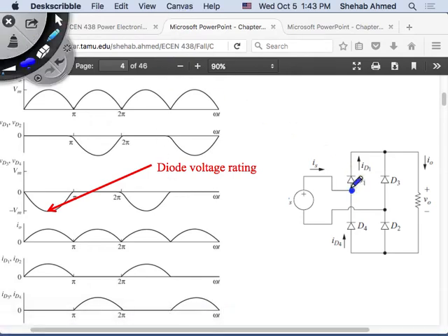So now we want to derive it. Typically, all you're concerned about is the source current. I'm the utility, I don't care what happens inside your converter. You do whatever you want. But you're consuming my current, so I need to make sure that you're not polluting my current, causing my power quality to be poor, right?